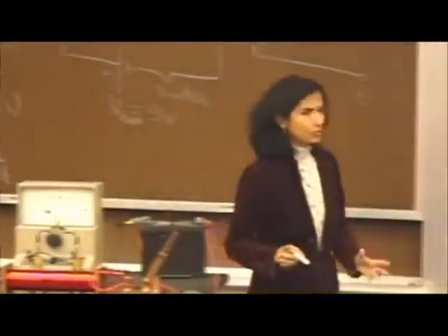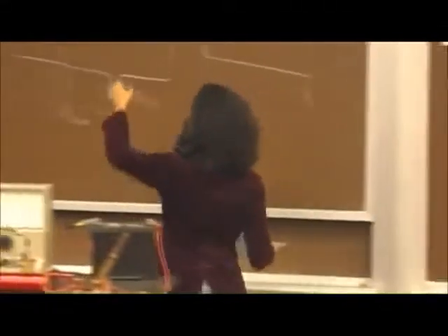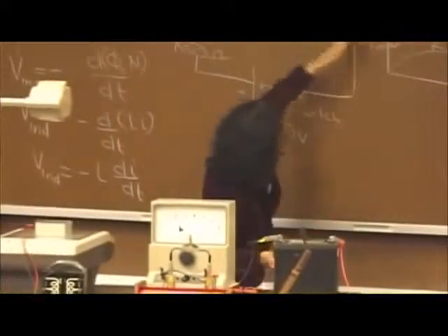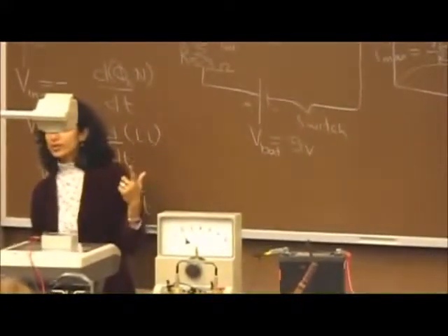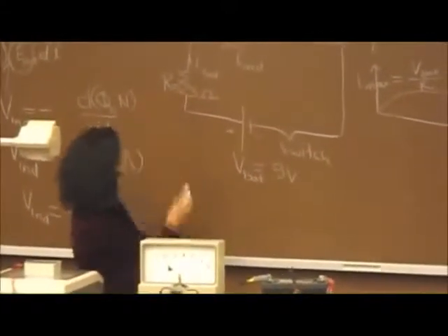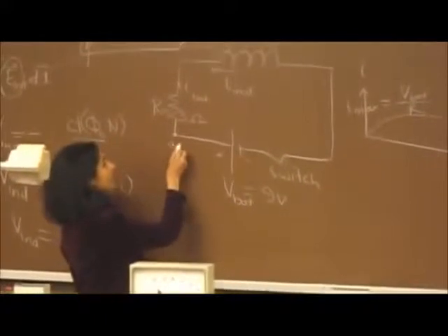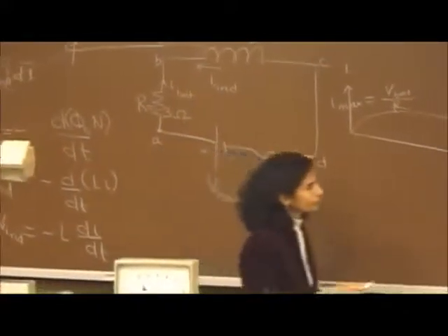All right, so now let's try to think about this problem mathematically, and all we are going to do is make use of Kirchhoff's rules. Remember we use Kirchhoff's rule. If you go through a loop, from here to here, here to here, here to here, and come back, all of the voltages should add up to 0, right? So let's start from some point. Let's say we go from here, A, B, C, D.